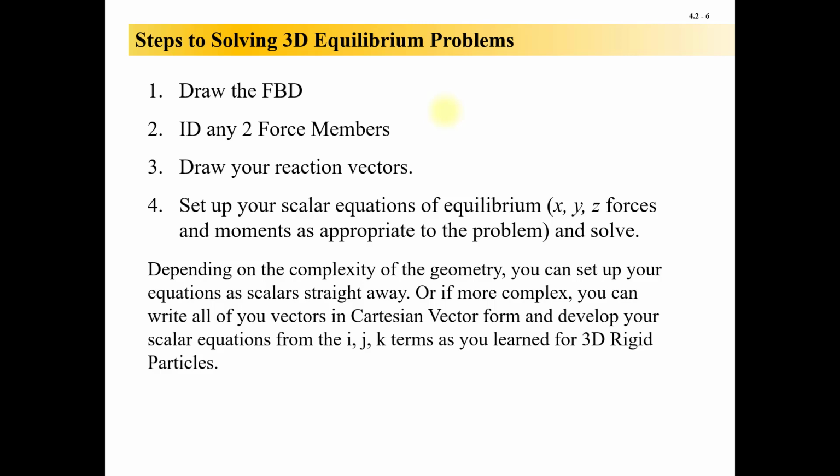Okay, and then just realize for 2D and 3D, moment vectors don't plug into force equations. They go into moment equations. Now, force vectors can find their way into moment equations because moment equations can be either due to true couple moments or forces times distances. So you can have force times distance. Every term in a moment equation should still have a force times a distance. Kip-feet, pound-feet, kip-inches, Newton-meters, kilonewton-millimeters, whatever it is.